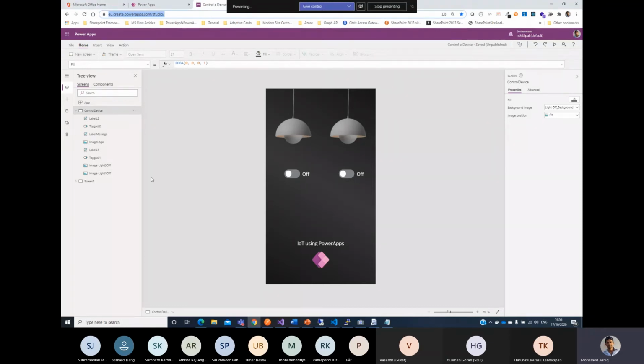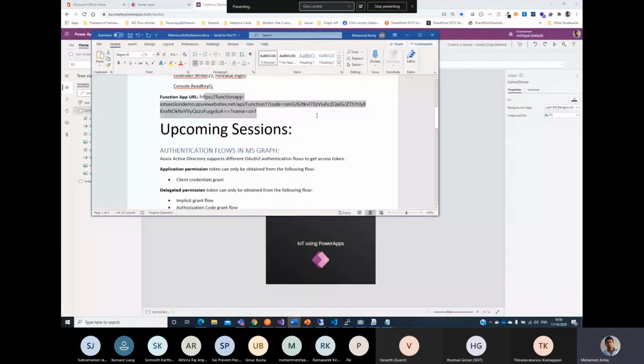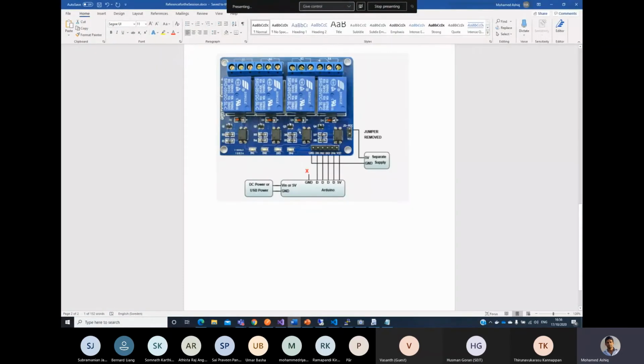So this is done, and I will quickly show the relay module which I've used. It is a 4-channel relay, and this one is actually created for Raspberry Pi. It is a 5-volt relay, and we have the jumpers here. I have already said that the voltage from the GPIO, if it is set to high, is only 3.3 volt, and since this is a 5-volt relay, 3.3 volt will not be sufficient. So in that case, what you have to do is remove the jumper here, and on the JD-VCC, you give 5 volt, that's again from the GPIO.